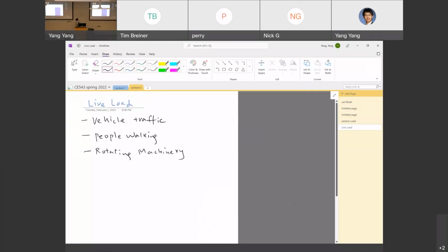As you can see here, when you design a building, you need to mitigate the vibration due to the occupants' activities such as dancing, some walking, or sometimes running. And you have to consider the natural frequency of the floor system. Actually, AISC, the American Institute of Steel Construction, published several guidelines on how to consider the vibration of steel frame floors.